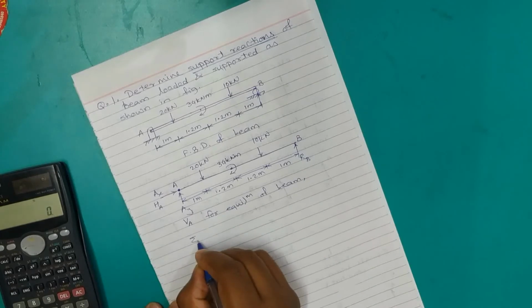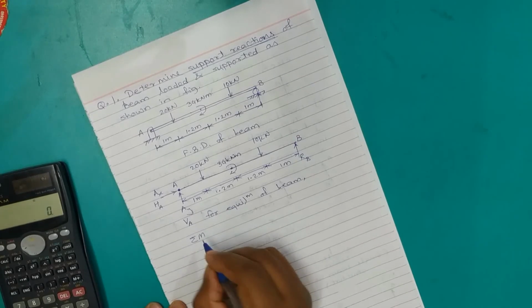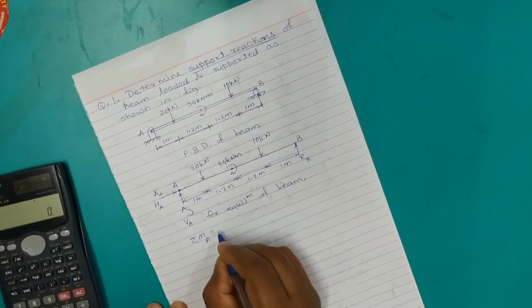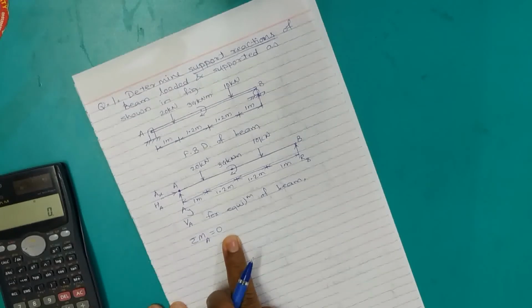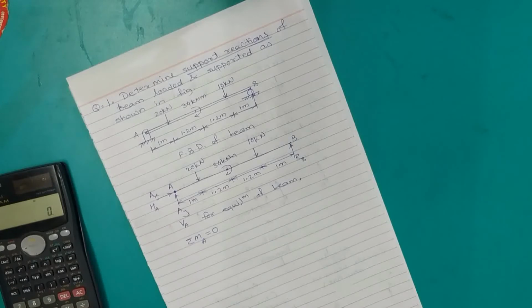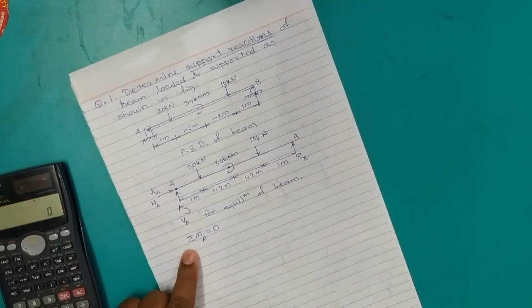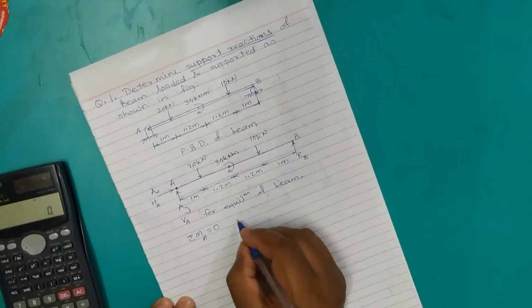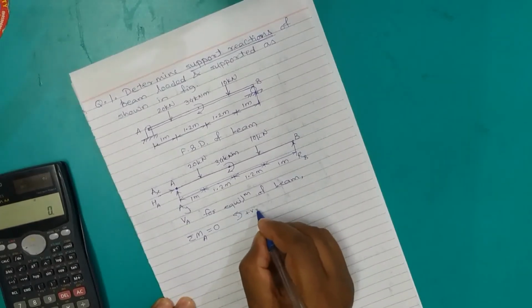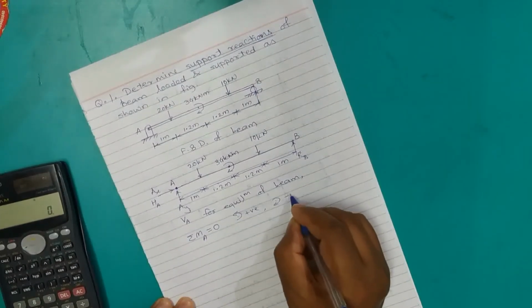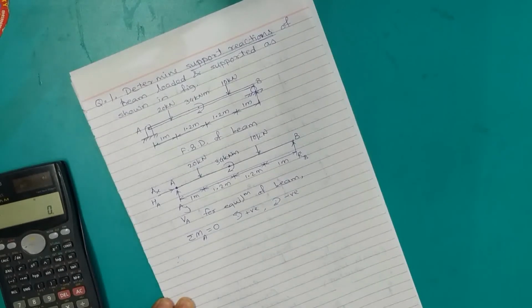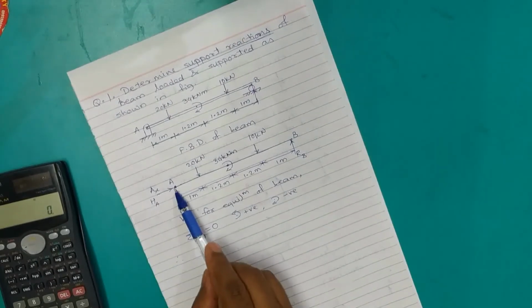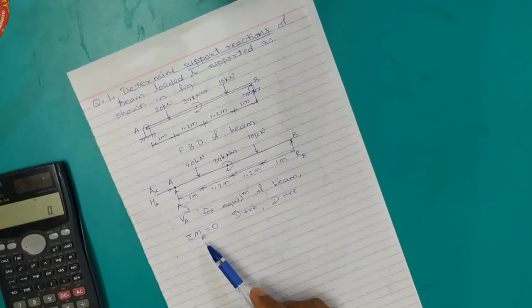So I'm going to write the first condition of equilibrium, summation M, specifically about the hinge point, equals 0. Remember, we are not finding how much the moment is. We already know that the moment of the entire system is 0 because the system is in equilibrium. So we are saying summation MA equals 0, where as usual anti-clockwise is positive and clockwise is negative. Why have we chosen point A for applying the moment condition?